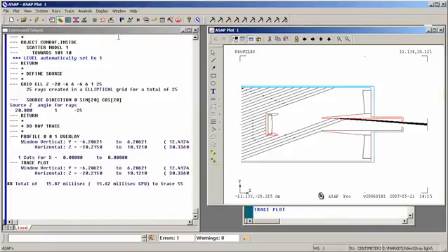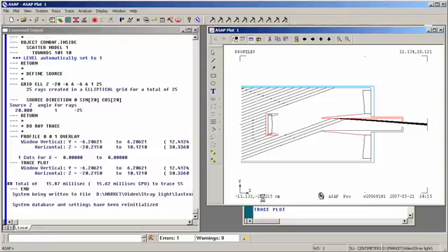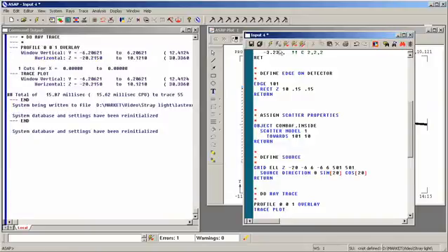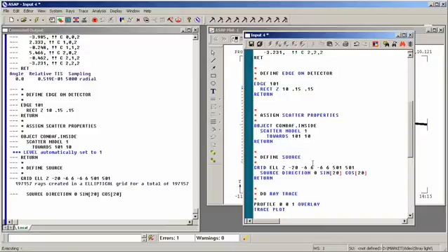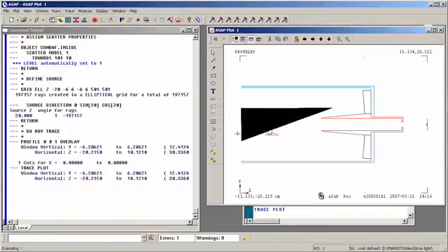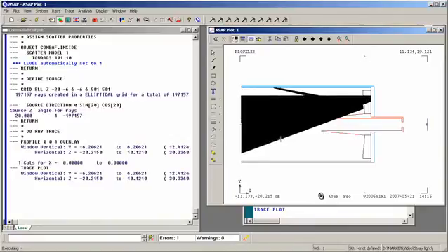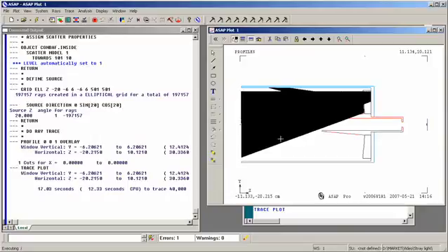To have a more realistic representation, let's put in a few more rays. We'll end what we had before, and we'll trace, maybe 501 by 501. Here comes our ray trace. Now the ray trace takes longer, of course, because we're tracing more rays, and the screen essentially goes black because we're tracing so many rays we're filling the entire screen. Not apparent in this is that a large amount of the time traced is being taken up by graphics. That is to say, the time required to make pictures of all of these rays.